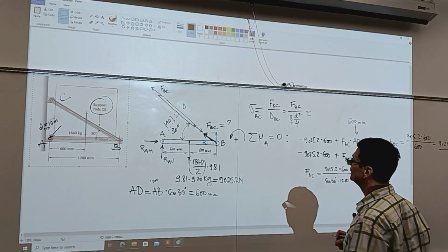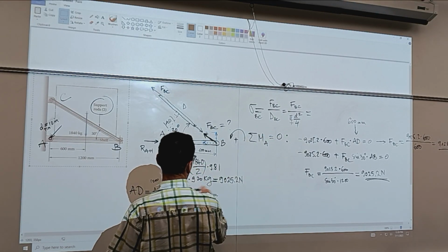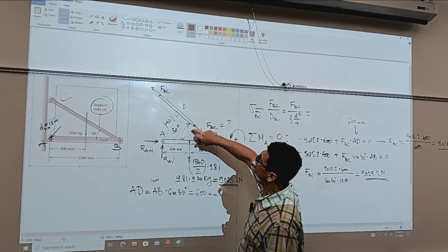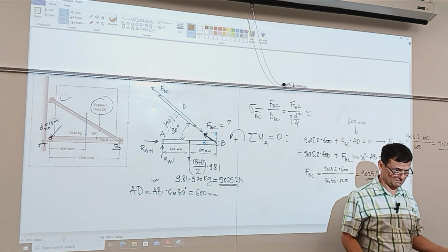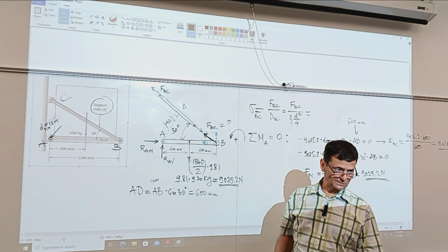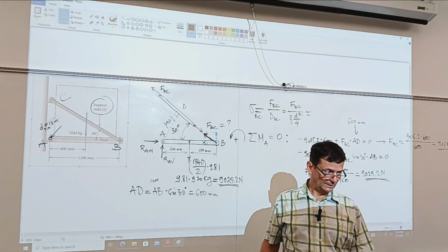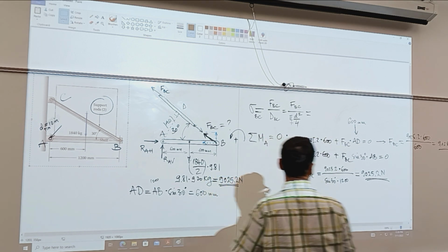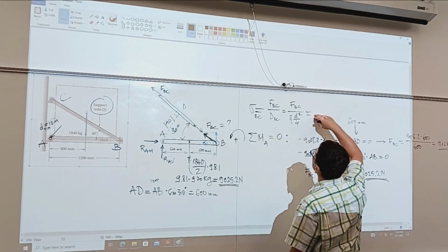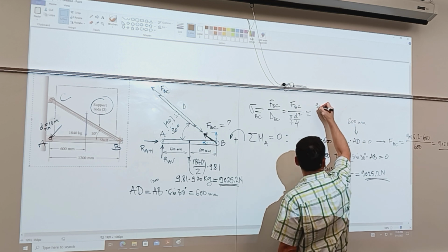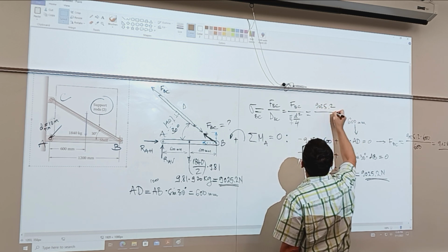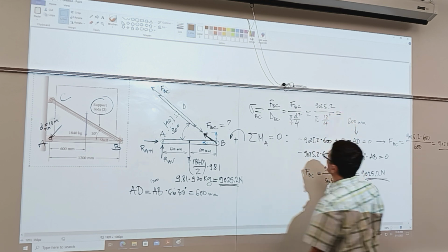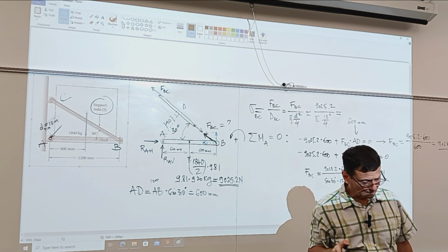And you know what? I think, have we divided this by 2? Yes, we're correct. Double check. Oftentimes, this trivial step is overlooked, like usually happens in practice. The simple things, a $2 ball causes most hassle by failing. Anyway, so we've got a force, we can calculate the stress. So it will be 9025.2 over pi 12 squared over 4. Okay. Remember this. Maybe you've been told about this.